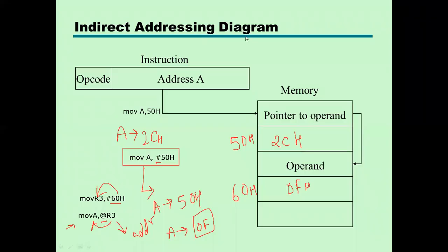In this slide, we are summarizing the effective way the data is handled by the microcontroller. I'm showing here 3 examples. This is the first example, where I have written one instruction called move A comma 50. Here, 50 is the 8-bit address of the source, and A is the destination. Register A is the destination. This type of addressing mode is called the direct addressing mode.